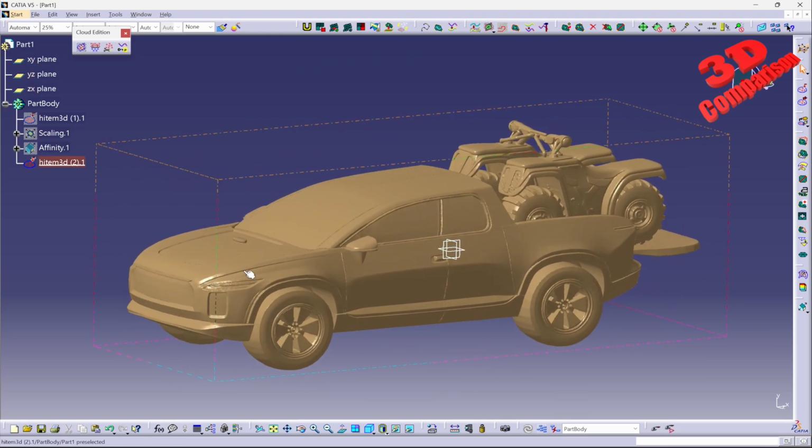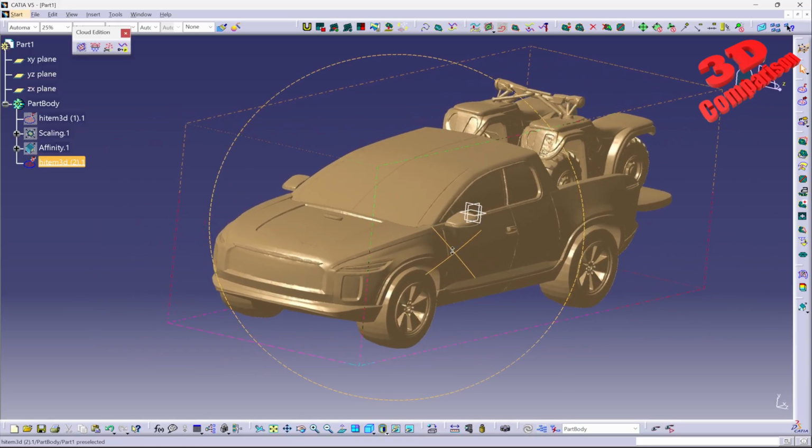You can define your boundaries. You can use either planes or sketches for that, and you can center that reference within those desired references. So this is how I would approach this car concept, where we can start with a generative AI model, load it within CATIA, but it's really important to define it at the correct scale.